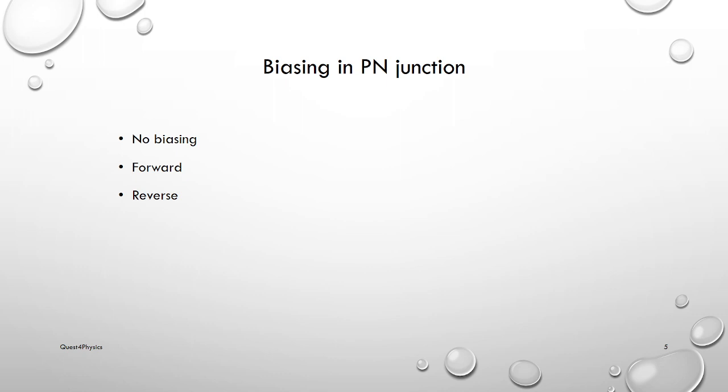Due to the gradient in the carrier concentrations, the majority carriers will diffuse in the opposite direction, and this process is called diffusion. The minority carriers will drift towards the p region and also the n region. This process continues until the system achieves thermal equilibrium. A depletion region is formed which is fundamentally free of charges, and an electric field occurs in the interface between them. Due to this electric field, a voltage arises, and this is known as the built-in potential voltage.